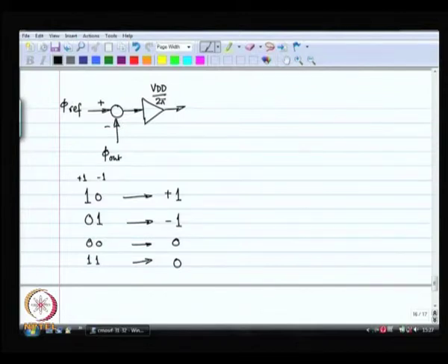right. So, what we have got to do over here is some kind of a digital to analog conversion. It's a crude digital to analog conversion that we need to do. We also have to do some sort of averaging in the process. Okay. So, the correct output of the phase detector is the average value of the plus 1 signal minus the average value of the minus 1 signal. That is the correct output of the phase detector over a given period, right.